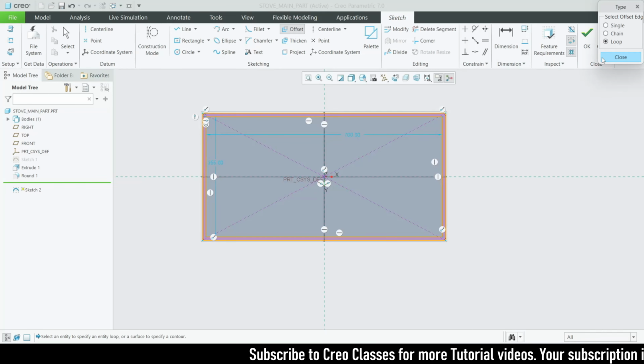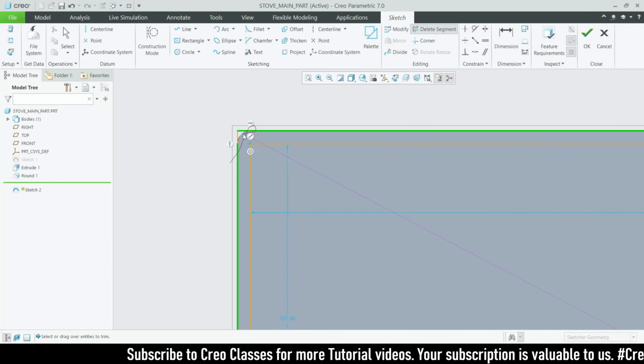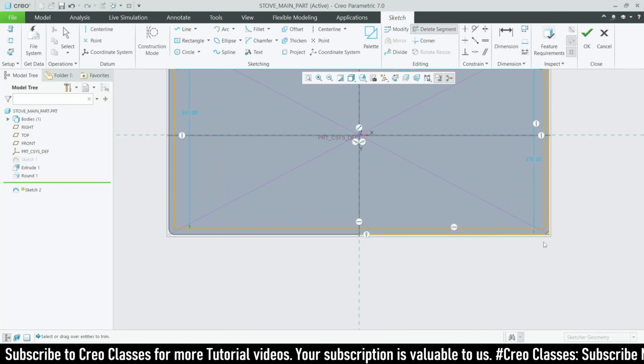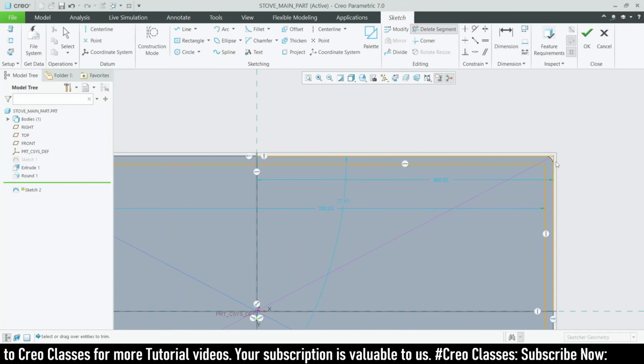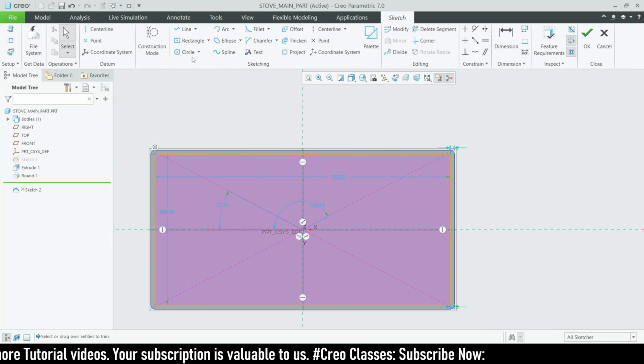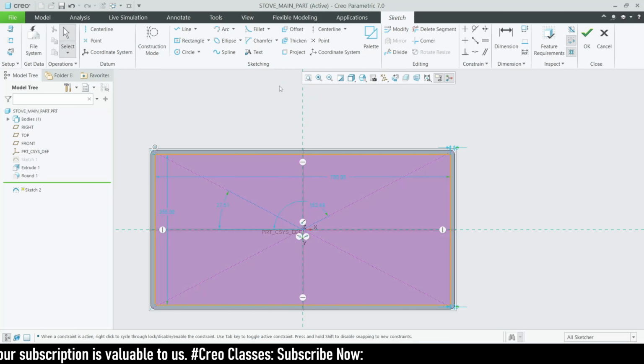Let's close all this and delete these projected lines, like the center rectangle we created. We don't want this anymore; we just created it for reference only. So we have completed our sketch. Then I want to create one more rectangle. We can take an offset of this also.